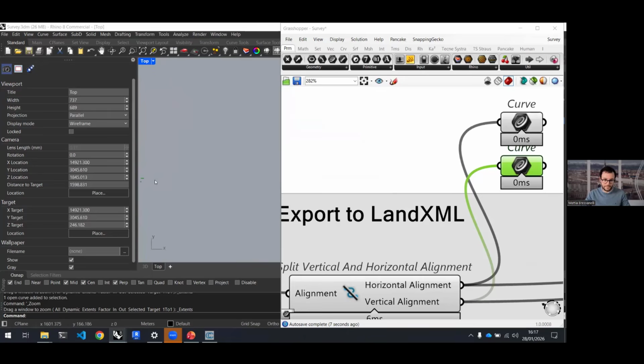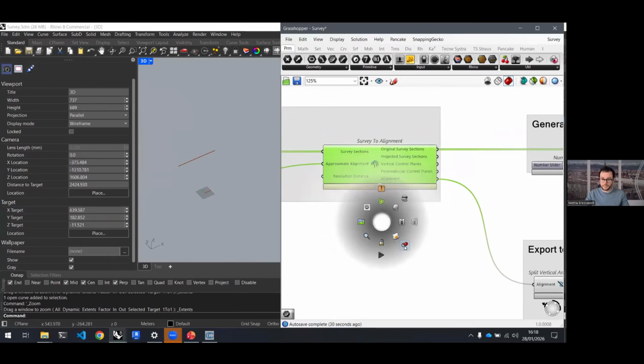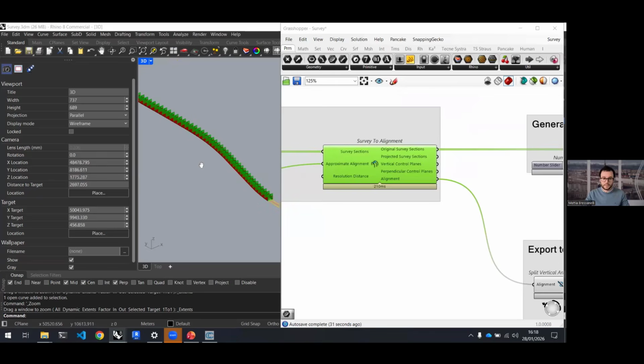So to work around it, you could imagine the x-axis as being the stations along the alignment, the vertical axis as being the elevation, and this is just the line that represents the profile. So then we can take these two polylines and join them together, and that's the 3D polyline that makes up the alignment. So let's go back to the tunnel.